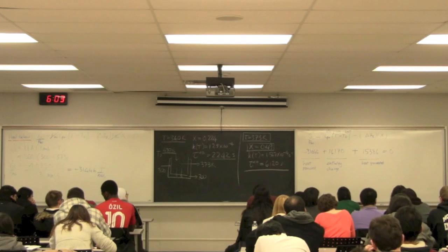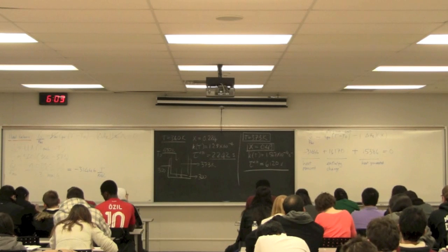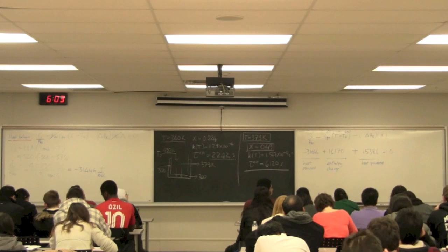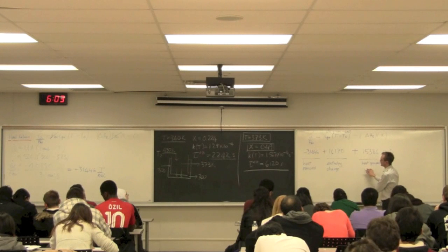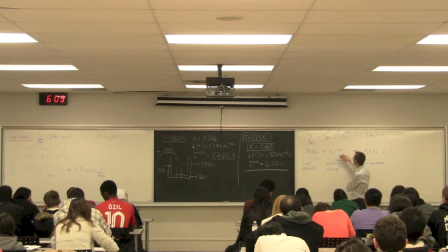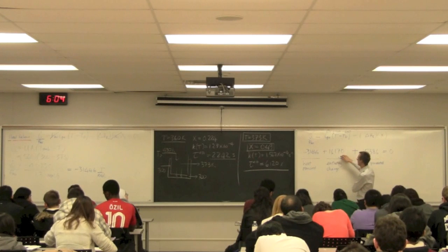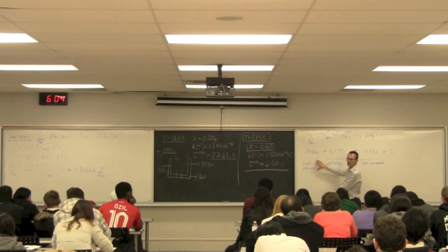So this isn't just a reactor, this is also a heat exchanger. Right? We're not simply removing the heat that comes from the reaction, we're also cooling the material in addition to that. So if I came in at a lower temperature over here, I could actually get away with removing less heat.